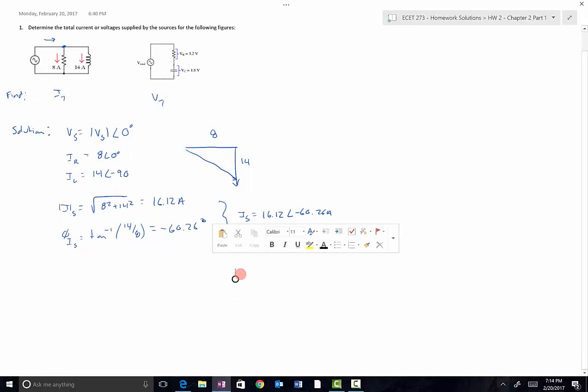For this other circuit here, we are going to use KVL. And overall, we know that this circuit has a capacitive nature to it, and therefore the current flowing through this is going to be in the first quadrant. Remember that the impedance diagram for this circuit is going to look something like this. We've got an R, we've got an X that's reactive, it's capacitive reactance, so it goes negative. So this is Z here.